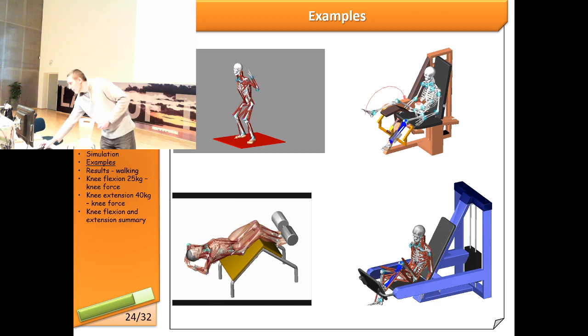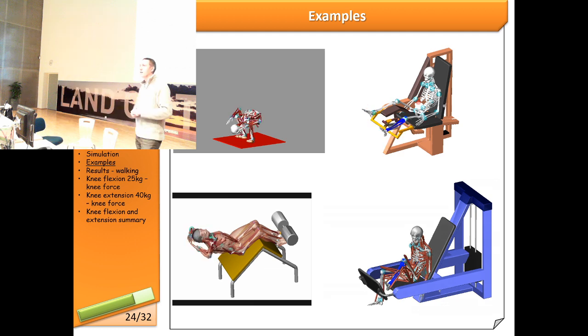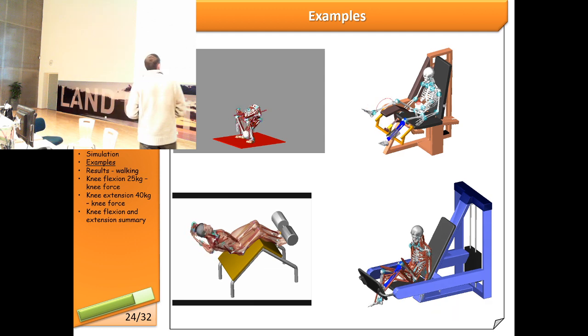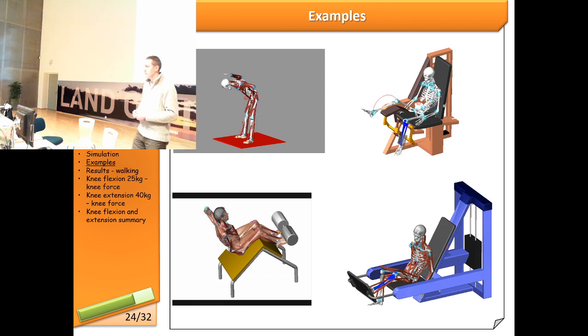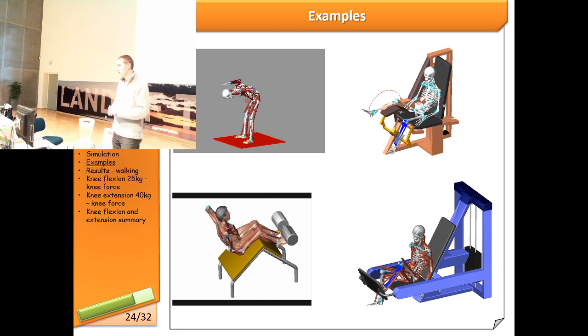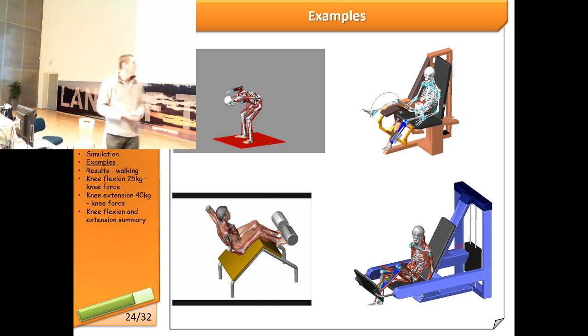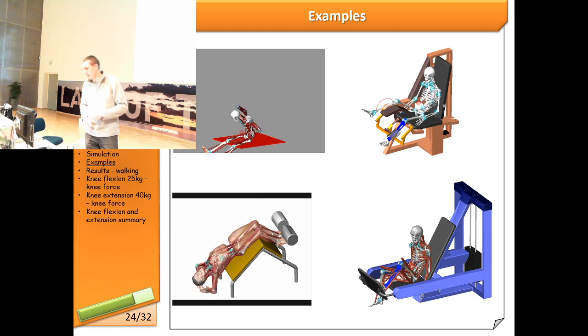The guy up here, who is just bending the knee and applying the load, also has a flexible bone, and there's a contact model or a sliding joint, I think, between the bone and the support. The loading was modeled as a torque applied, which would normally be the rope pulling from the weights. So that's how you can get around it. He doesn't have any muscles on the upper body because they are not necessary. It's basically just the animation part, but the muscles were applied on the lower body. Here they are hidden for clarity.